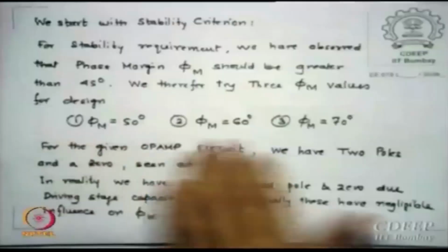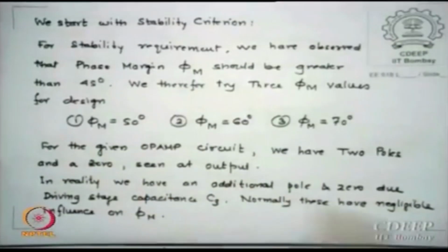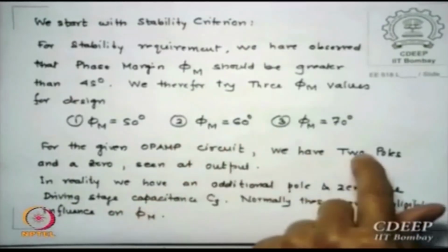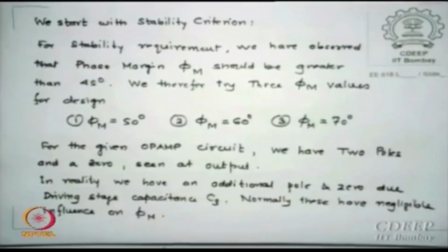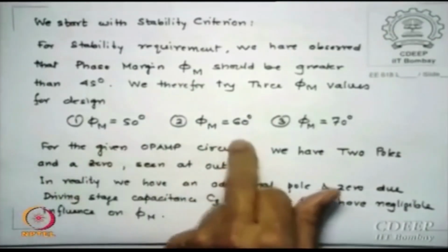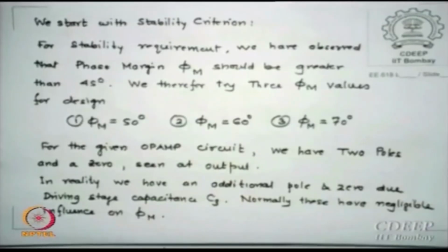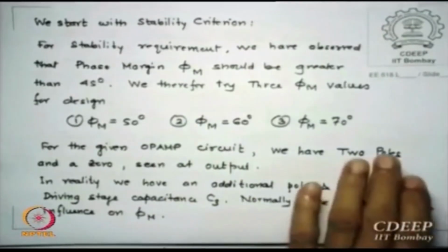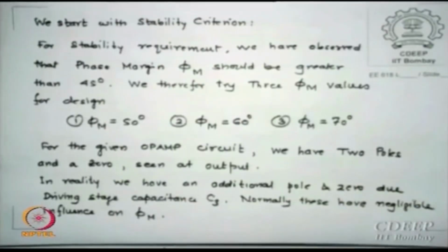If you choose differently, all the other values will correspondingly shift, because GB, P1 and P2 will change. So everything will change, it does not matter, some other W by L will appear, but you must decide the margin for yourself. I had chosen these 3 values for initial calculations. The final design is for 60, but I will just show you how much variation the poles will get if I choose 50, 60, or 70. Even 75 is not out of the question, but as I said, it creates some other problems, and therefore preferably keep to 70.